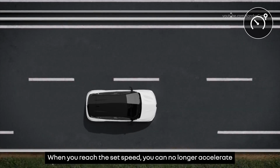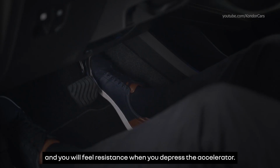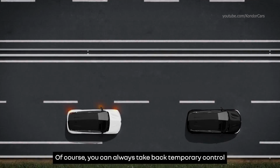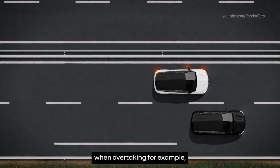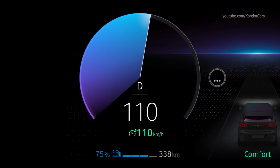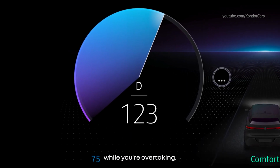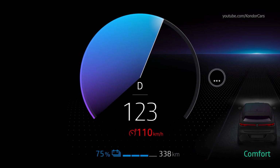When you reach the set speed, you can no longer accelerate, and you will feel resistance when you depress the accelerator. Of course, you can always take back temporary control of the vehicle's acceleration when overtaking, for example, by firmly pressing the accelerator pedal. You'll see the speed limit flashing red on the instrument panel while you're overtaking. To return to the set speed, release the accelerator pedal.